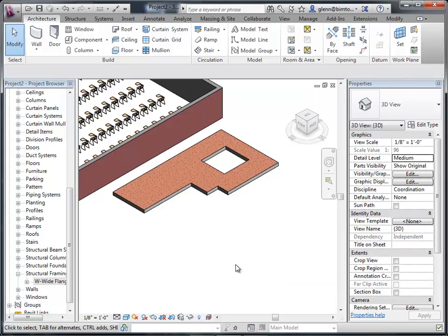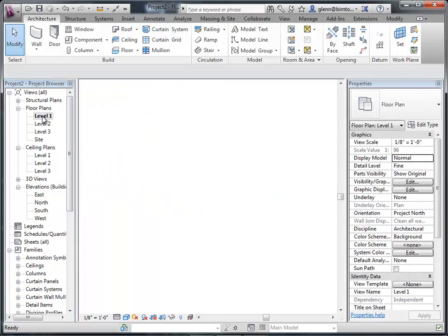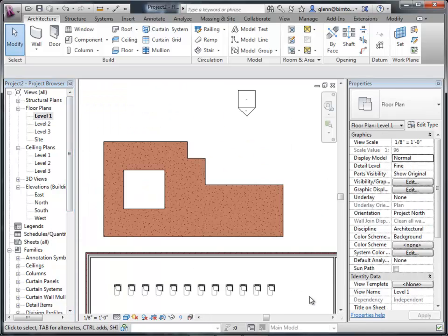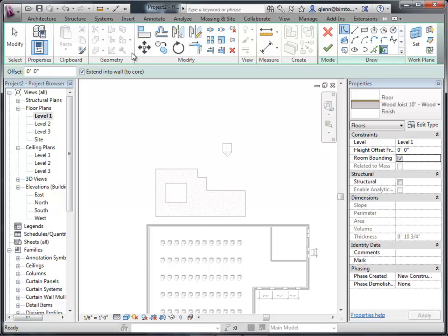And what I will recommend for this is actually just go back into the floor plan view. We'll use a slightly different variation on this thing. Let me zoom on out. What we want to do is choose a floor. But instead of just drawing the floor, a really good way to do this is this guy over here, the pick wall tool. The pick wall tool is incredibly useful because it'll find where the boundary of that floor is.